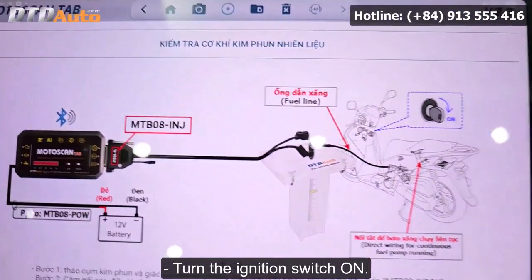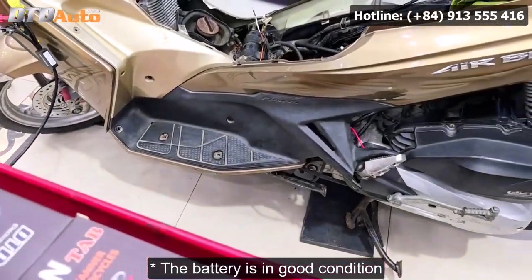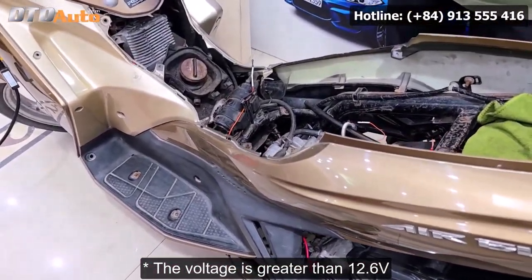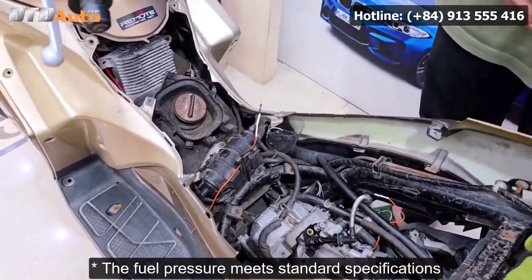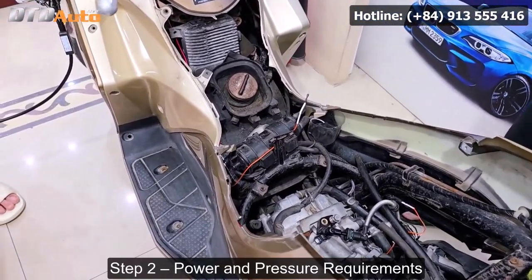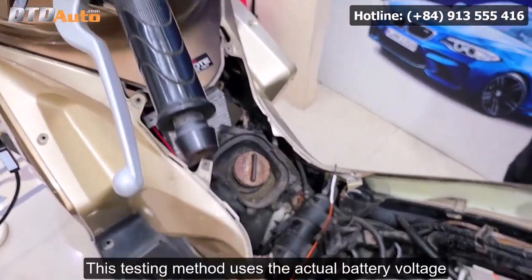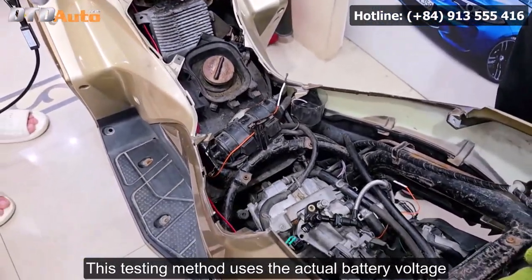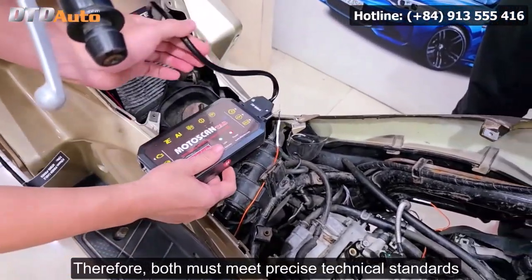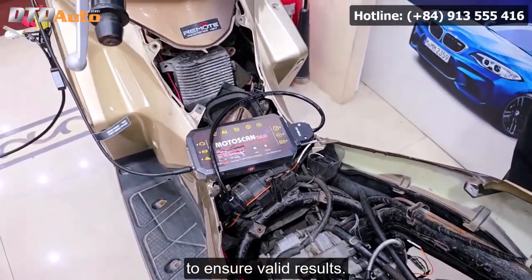Turn the ignition switch on. Ensure that the battery is in good condition. The voltage is greater than 12.6 volts. The fuel pressure meets standard specifications. Step 2. Power and pressure requirements. This testing method uses the actual battery voltage and in-vehicle fuel pressure. Therefore, both must meet precise technical standards to ensure valid results.